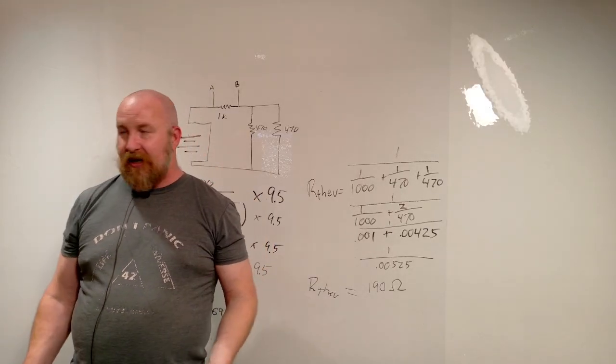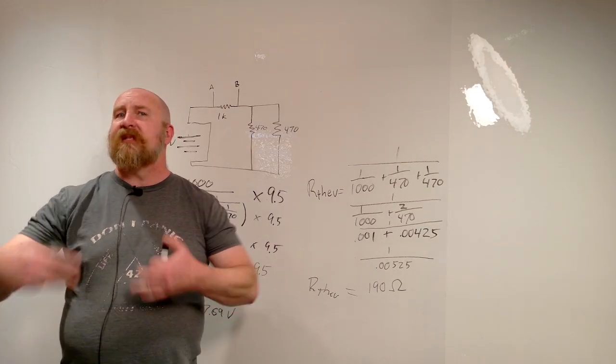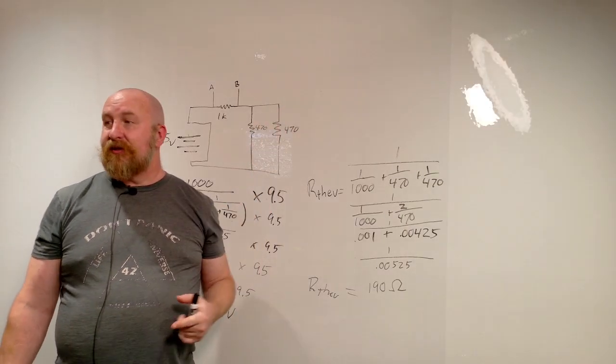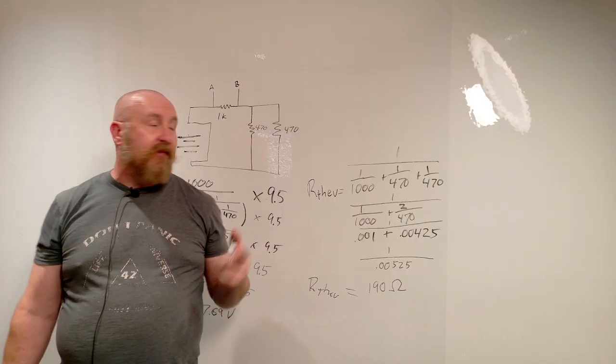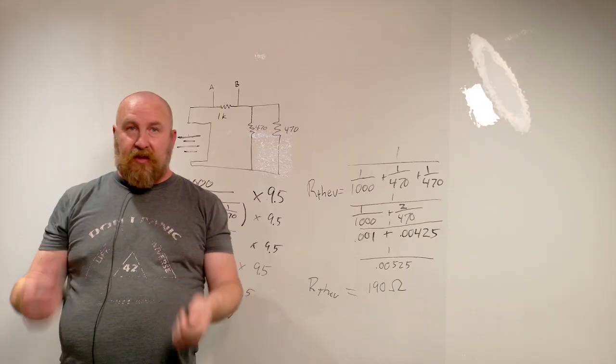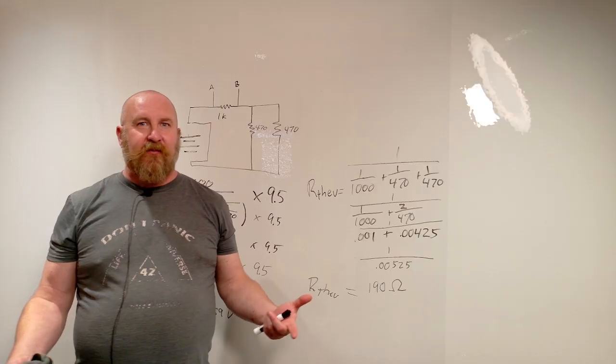Yeah. And so when you go and do this, you can analyze the circuit and decide, okay, this is what it should read when I hit this. If it's reading something else, it means I've fried something. It means something's not working. If I fried this 470 ohm resistor here, I would get a very different voltage drop across here.